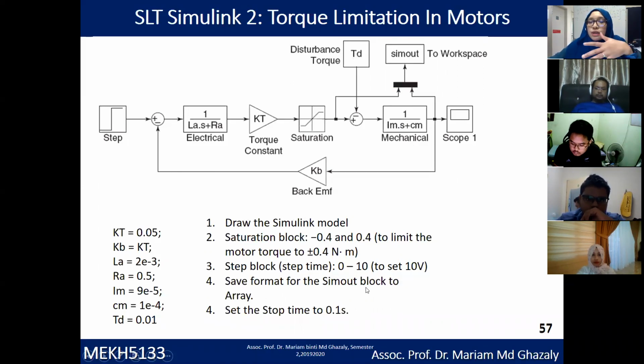It's a similar concept when you have an actuator. An actuator, actually the coil will only withstand plus minus 2 ampere. So you don't want to exceed to 3 ampere. So you set it as an initial saturation point. Means that if you were to actually apply the step here, more than 2 ampere, then it won't go up to 2 ampere. It will cut off that value.